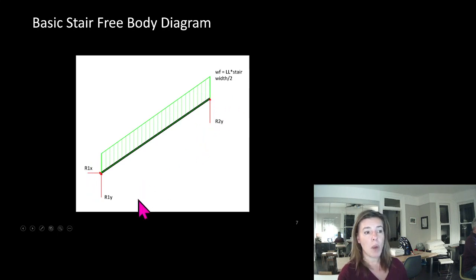So we'll often, where possible, look at doing a pin roller. We will actually analyze it with the load on it and see what the movement is. If the movement can be a millimeter or two, because we've allowed it to move, often we'll put the reaction up here and the roller down here. And if this moves just the tiniest little amount, we're good. If this tries to move a meter, well then we have to do a pinned condition, and we will probably develop very high reaction forces.